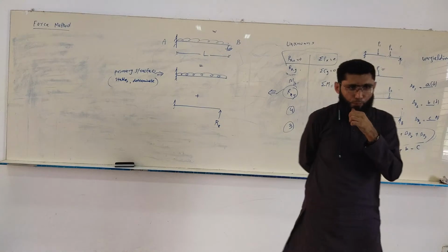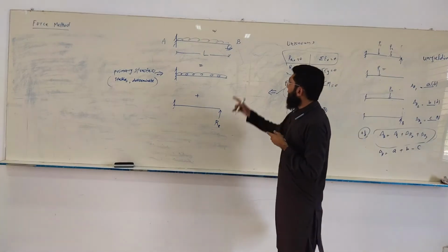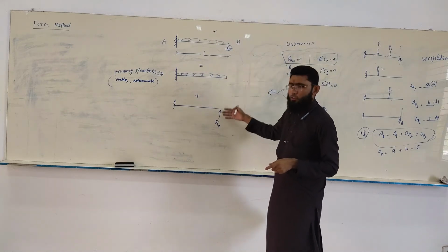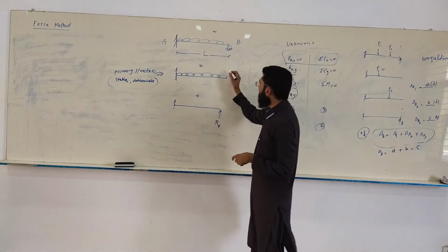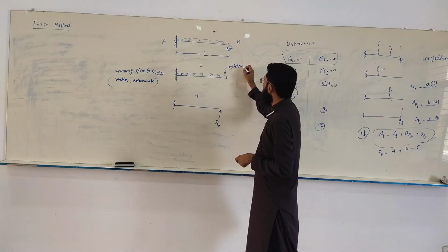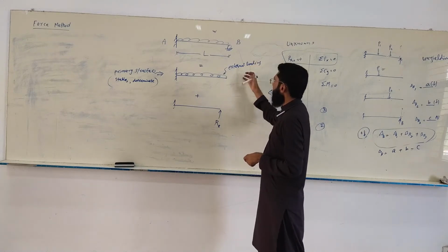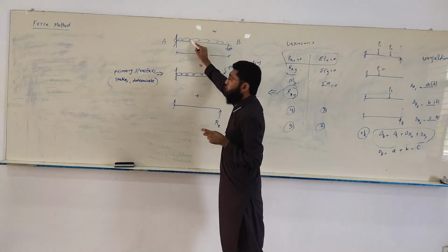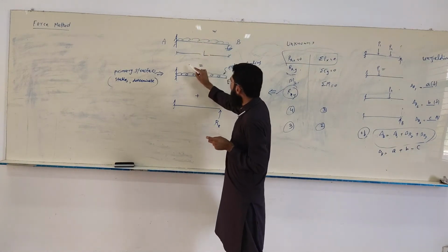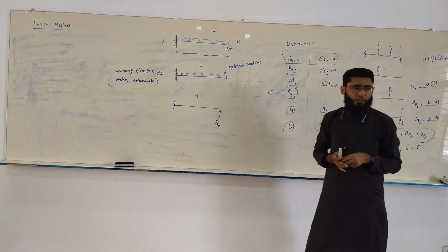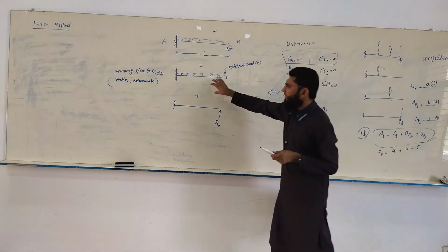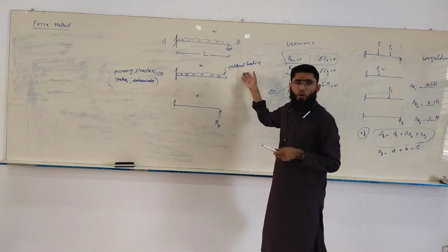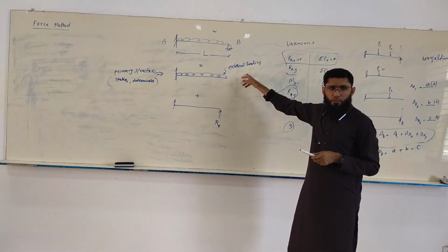All right. So we were pretending that the displacement at B is not known, although it is, but we just try to find it by a superposition method, and then what we do is we treat with this external loading in the first step. So whatever external loading is applied, if the given beam consisted of, for example, another point load over here, another point load over here, we would have considered all those loads in this first part. So this is primary structure subjected to the actual, or maybe external loading, or maybe sometimes you can call it the actual loading. Okay.